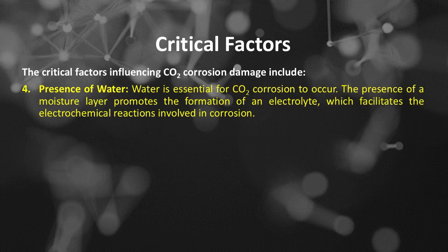Number 4 is presence of water. Water is essential for CO2 corrosion to occur. The presence of a moisture layer promotes the formation of an electrolyte, which facilitates the electrochemical reactions involved in corrosion.